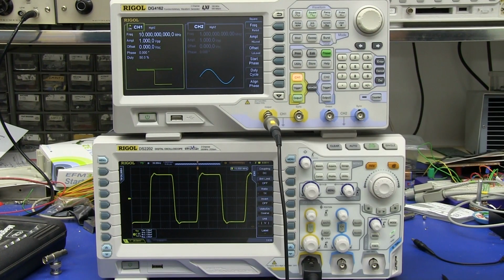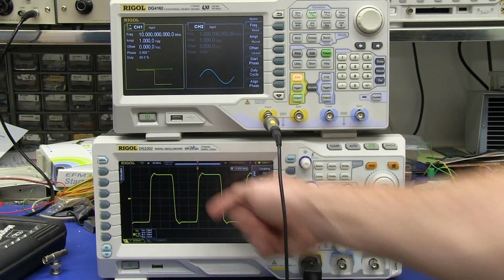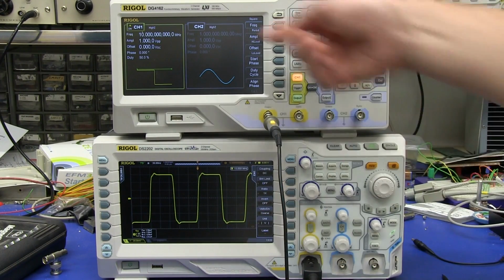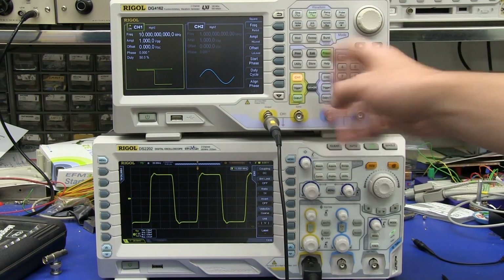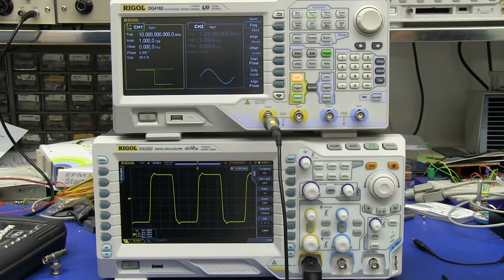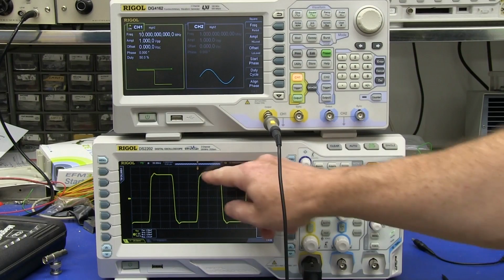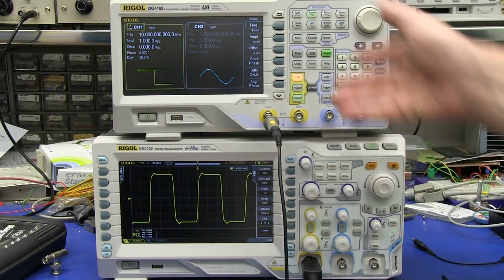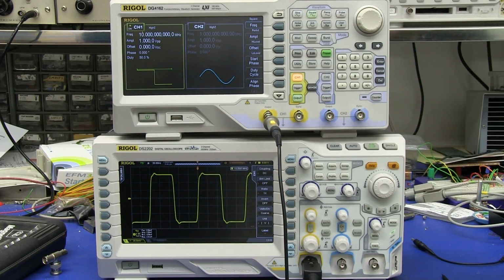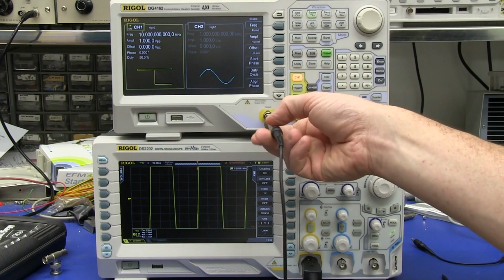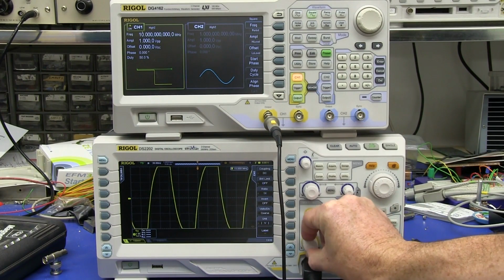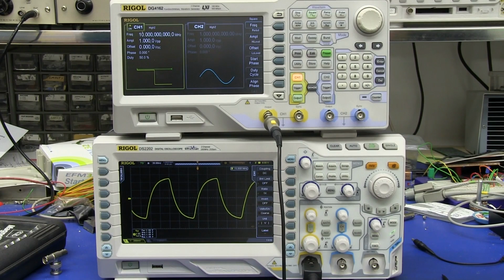And of course that bandwidth limit is going to kill any high frequency content, like this square wave, for example. Here's a 10 megahertz square wave on ×10 mode, so the bandwidth of our probe is 350 megahertz, and of course it looks like a square wave, and we can see the overshoot and the actual signal fidelity in there. But if we switch it to ×1, look at that. Bandwidth limit of that ×1 probe.